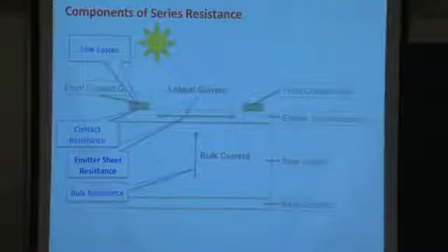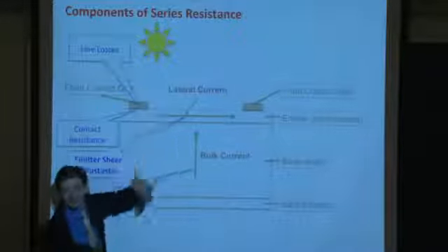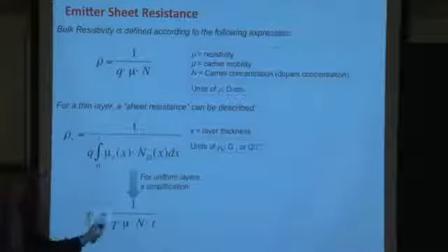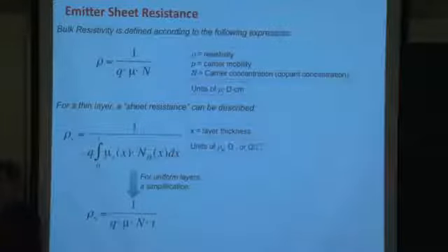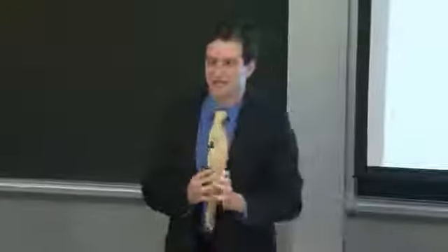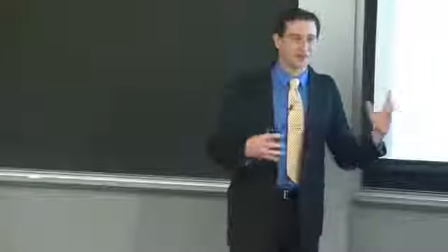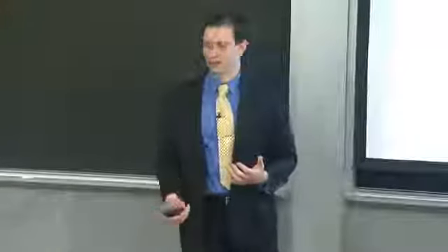Its electrical properties are very, very poor. So if I make this layer too thick, sure, I get rid of my emitter sheet resistance term, but at the same time, I'm killing my quantum efficiency in the short wavelengths because I'm not able to absorb those short wavelength photons and convert them efficiently into electron hole pairs. So this is a story about co-optimization of different device parameters.